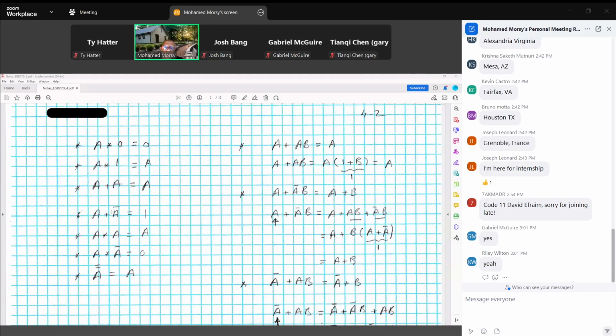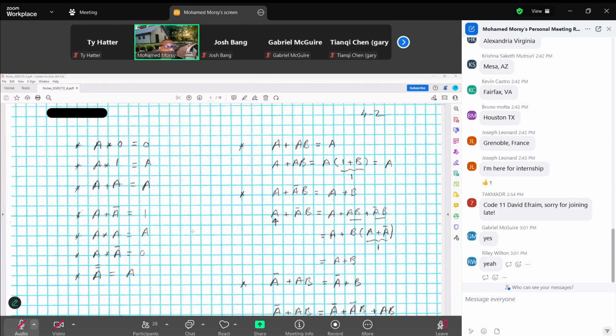When you simplify this expression using these properties, you may discover that the output is connected directly to the input, just a wire, despite the expression giving you a lot of gates. When you simplify, you see repetition, so you skip the repeated terms, and with other properties as we will see, you reach the same result.